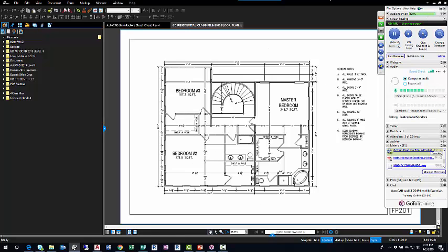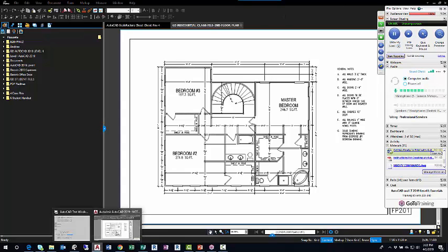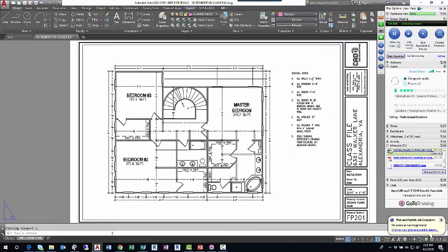I'm going to minimize my PDF viewer here, or I'll just bring up AutoCAD because I'm not sure which one. I don't want to minimize the wrong thing. If you are printing to an actual paper plotter, you of course wouldn't see what you just saw there, where the print preview or the finished plot comes up. But you will hopefully see this in the bottom right corner. There's this little plot and publish job complete, no errors or warnings found, and that's a good thing.